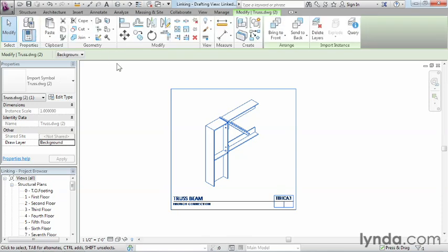But the reason why I bring that up is if we happen to have inserted this in, then it would have automatically increased the size of our Revit drawing file. At its surface, when you think about how big an AutoCAD file is and you insert it in, that doesn't seem like such a big deal. But if you insert 50 or 60 of them, you can guess how much bigger your Revit drawing file size could become. By linking this in, it doesn't actually add any size, any megabytes, to the Revit file size.